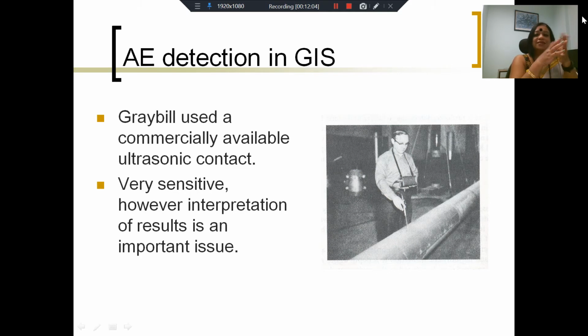So inside cities, inside crowded areas where you do not have control over the movement of humans or animals, that kind of clearance may not be possible. And therefore, we have what are called gas insulated substations. We'll talk about gas insulated substations in greater detail later. Gas insulated substations use pressurized gas, most often sulfur hexafluoride, or some combinations of SF6 and nitrogen or other inert gases as the insulating medium.